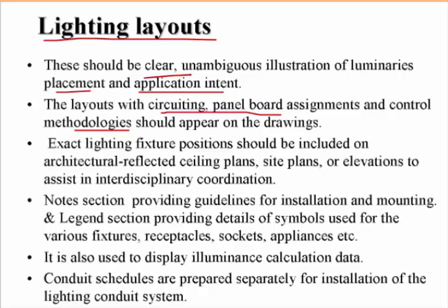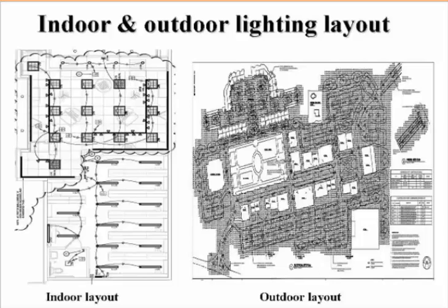You need exact lighting fixture positions, node sections that provide guidelines for installation and mounting, also used to display luminance calculation data, and conduit schemes are prepared separately for the installation of the conduits itself. So there's an example of an indoor and an outdoor lighting layout. So there's the indoor lighting layout and the outdoor layout, as you can see over there.